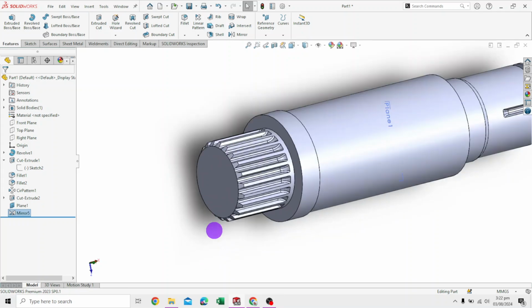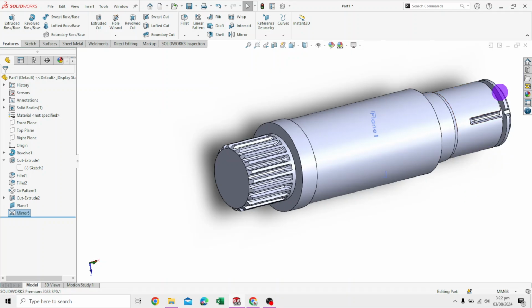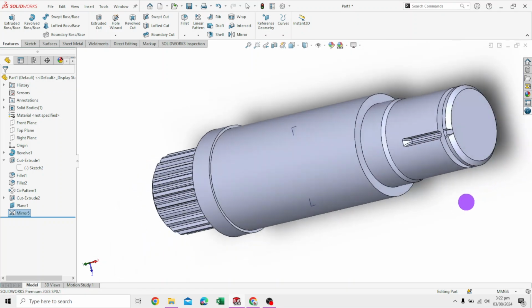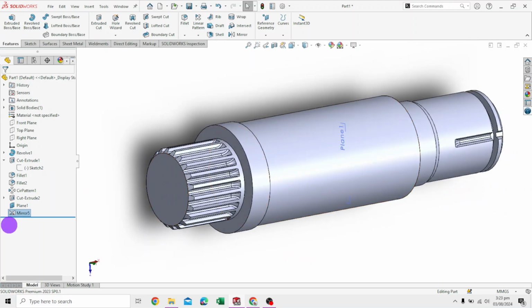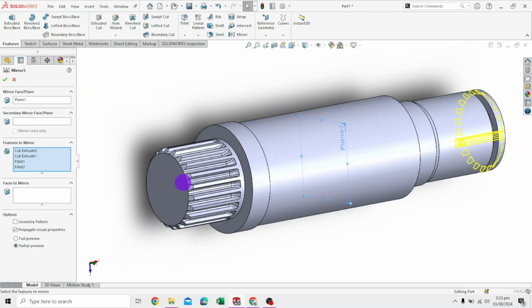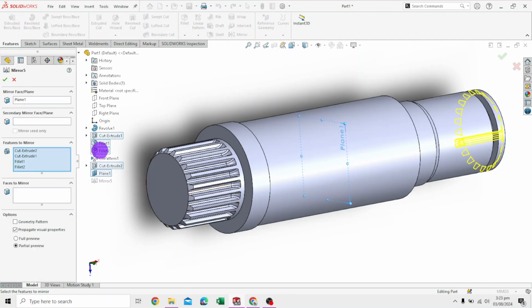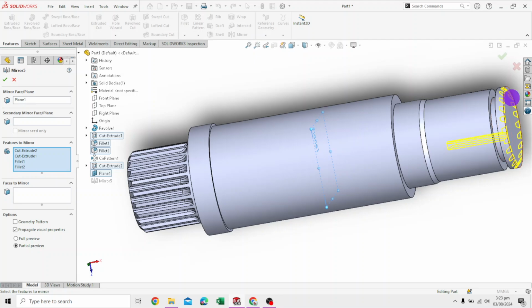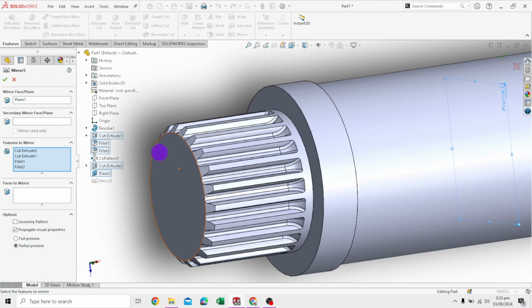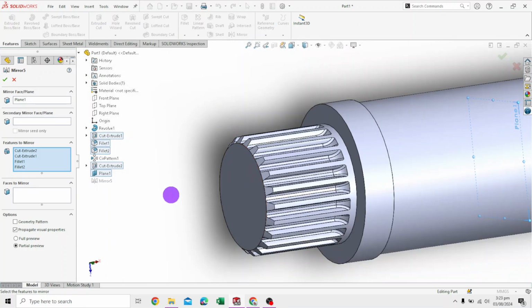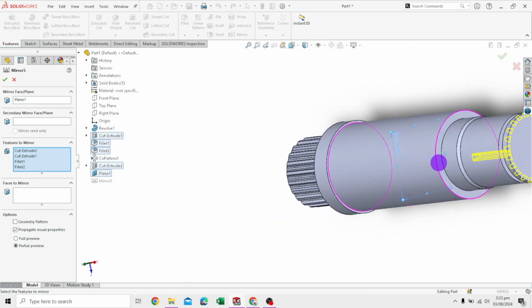okay, so for some reason it's not mirroring all these on that side, but it was able to do this. Basically, I've mirrored what I can. I'll just apply another pattern. So I've mirrored just the main two that we cut out, as well as this slight slanted cut that we made here on these. So now that we've got one tooth here, we can just apply a circular pattern over there.